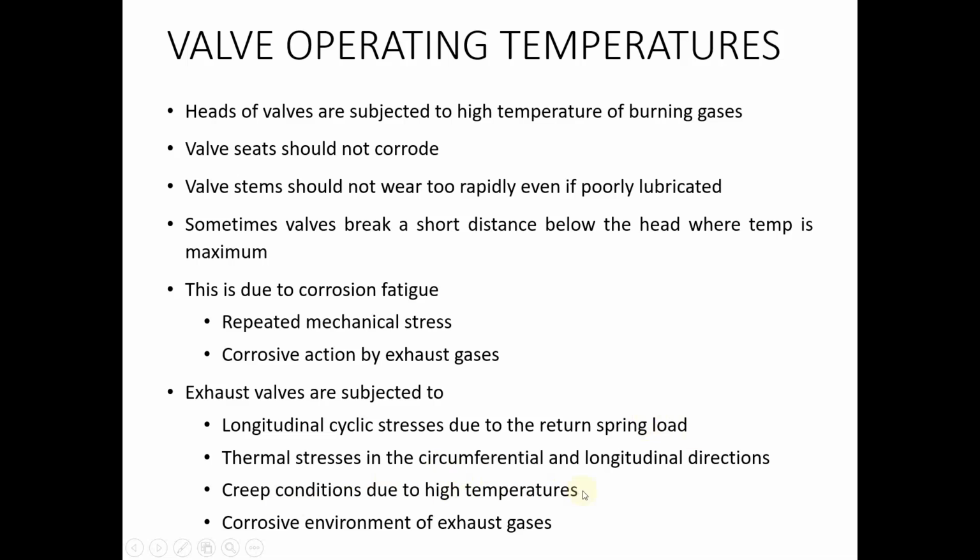And there are the creep conditions due to high temperatures and the corrosive environment of the gases. So usually valve failure occurs at the exhaust valves. Inlet valve failures are very rare because temperatures do not rise very high, and the corrosive exhaust gases do not come into contact with the inlet valves. So inlet valves are safe, and exhaust valves experience failure due to corrosion fatigue.